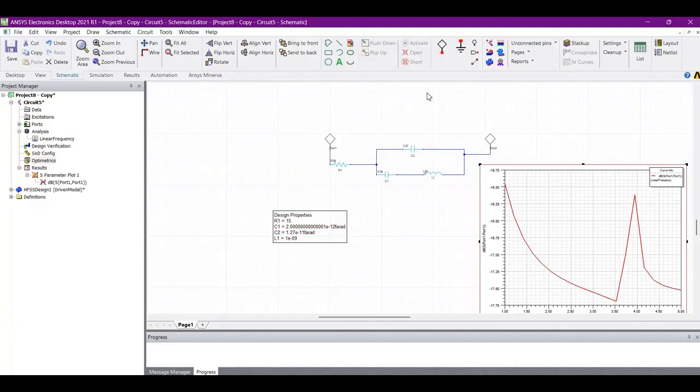So this is the story of how to make the equivalent circuit of a metamaterial absorber. So in today's lecture we have seen how in HFSS to provide the boundary to do the analysis of metamaterial absorber, how to insert the formula in output variable to get the curve of absorption, and how to draw the equivalent circuit and its values. Thank you.